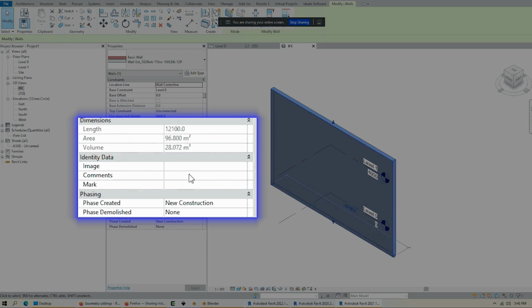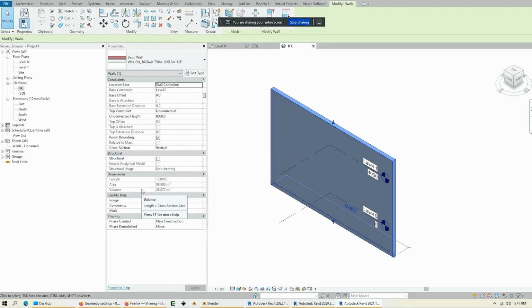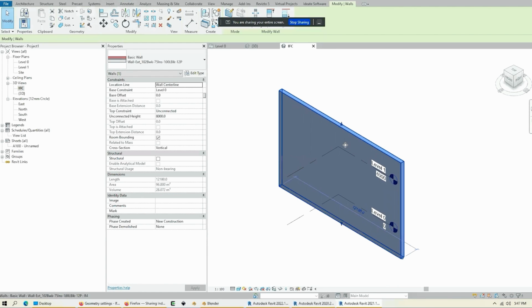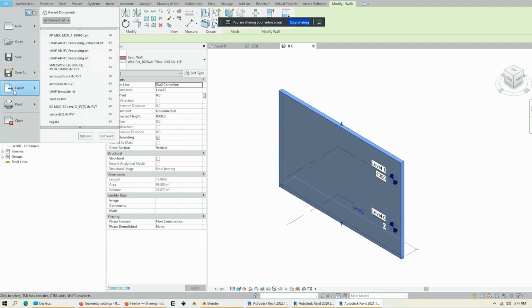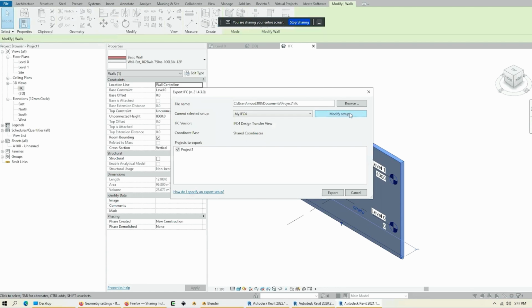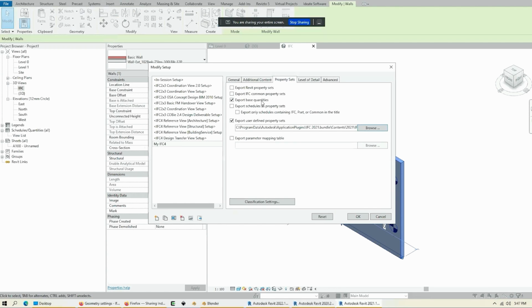Now, without looking at this value, would you actually know if that's a side area, a whole area, including top and side and bottom? Is it a gross? Is it a net? I don't know, unless you go check it in more detail. Well, actually, I do know the answer, but let that be an exercise for the viewer. So anyway, the point is that IFC has defined these standard quantities used for quantity takeoff. Again, another great reason to use IFC4, because IFC2X3 doesn't have it. So if you enable that, you will get that for free.